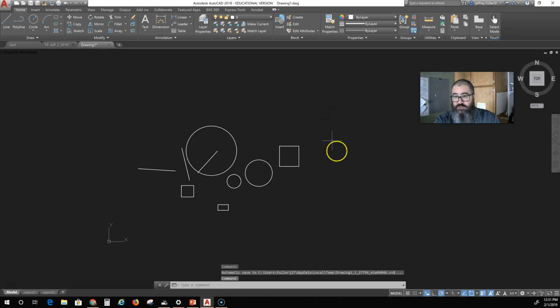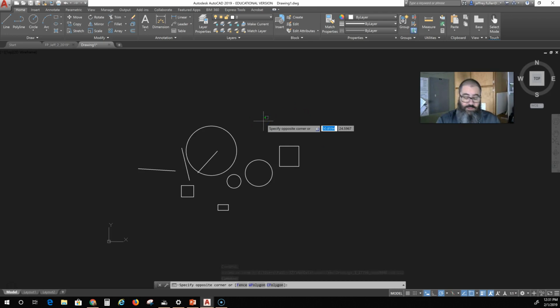In order to use it, again, get into your screen, click in an open spot, and then type just the letters FS this time. Click the enter button, and now what it'll do is it'll select all the geometry that is connected to the geometry you select. So if I want to select this circle and everything that is connected to it, I click and you see it also selected this line that runs through the edge of the circle right over here.